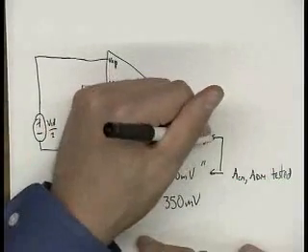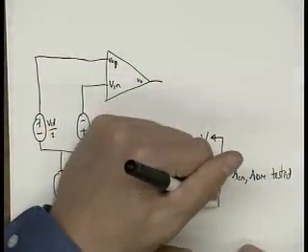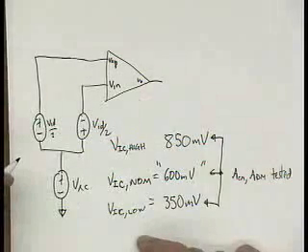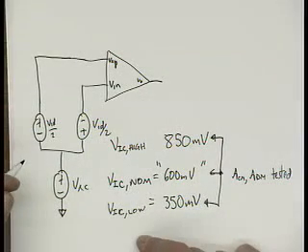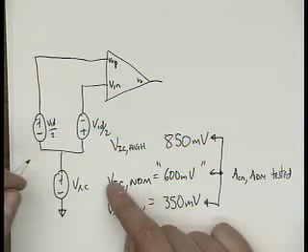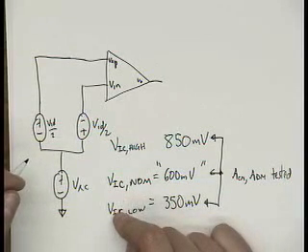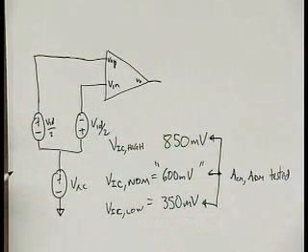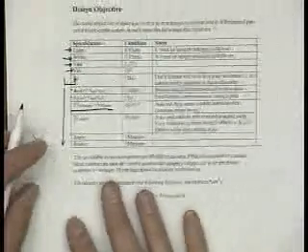So over all three of these corners, your differential mode gain and your common mode gain specs have to be met. Okay? That means that there's a relatively large input common mode range requirement on your amplifier. Okay? So that's this.